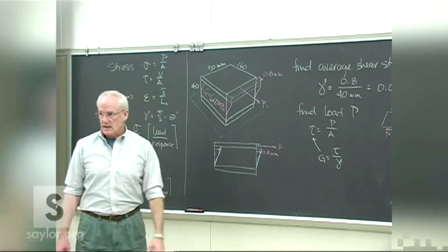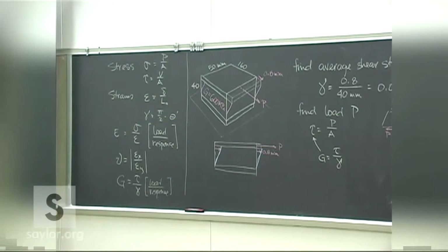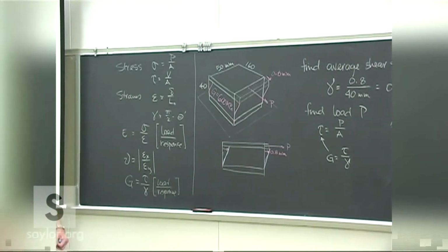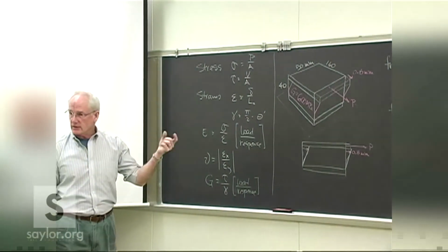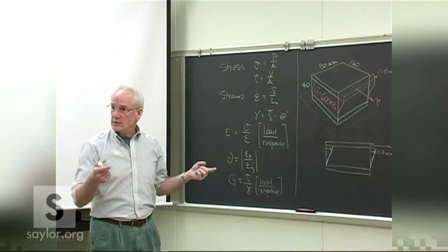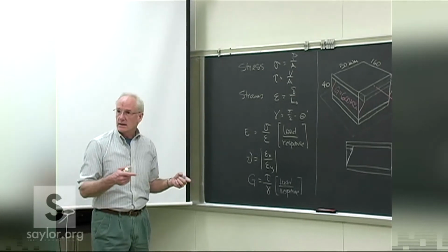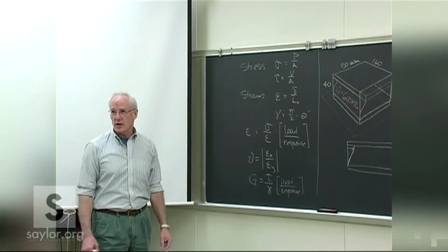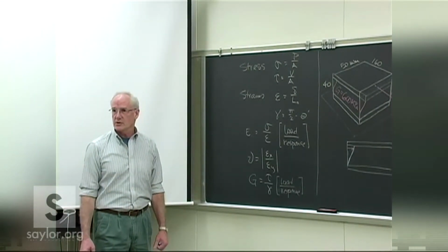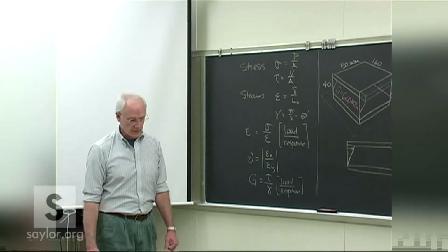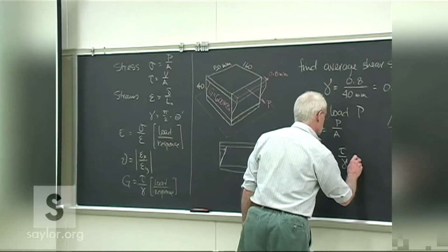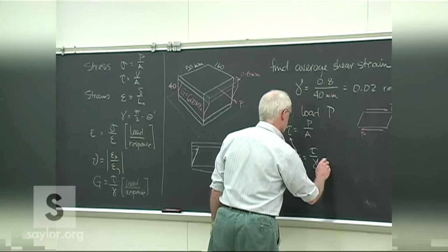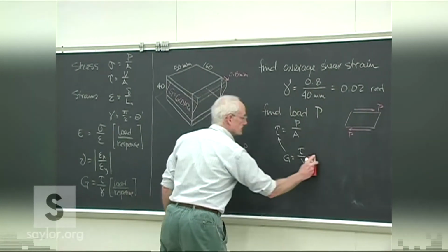You don't need that kind of precision coming out. And you have to be careful about that, because if you send a dimension drawing down to manufacturing in your company, and you have an extreme precision on it, because there's so many sig figs, they'll try to build it to that, and they'll charge you for that effort. And if you put a lot of precision in, it takes a lot of machining expertise to finish that, and they'll bill you for it.